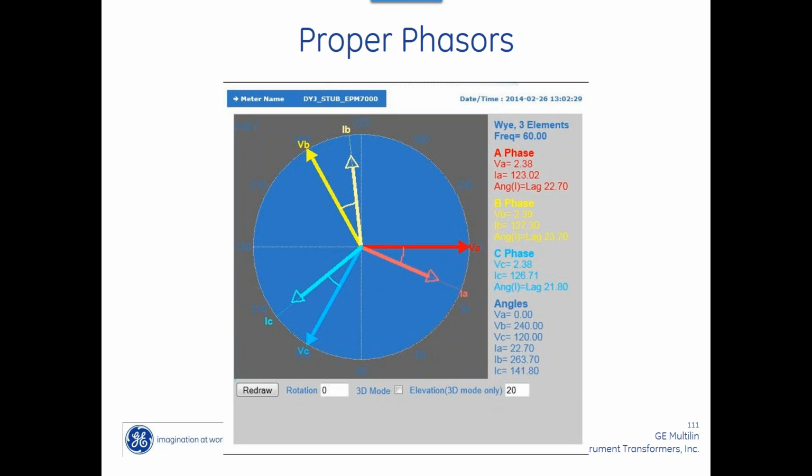While y'all are thinking about it, I'm going to answer this question. I personally don't like split core CTs because you're breaking the connection on the iron core and it does not give you as good an accuracy.